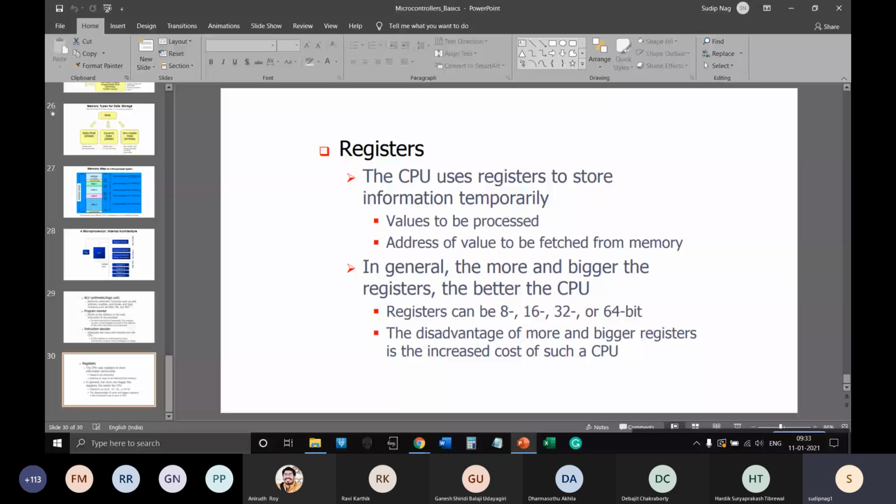Logic 0 could be 1 volt also, if the power supply is much more than 1 volt, obviously. That 'if' is a very conditional statement and is important. If your power supply is 5 volt, then 1 volt could be considered as logic 0, and that can be defined by the noise margin definition. Also, 5 volt means logic 1.